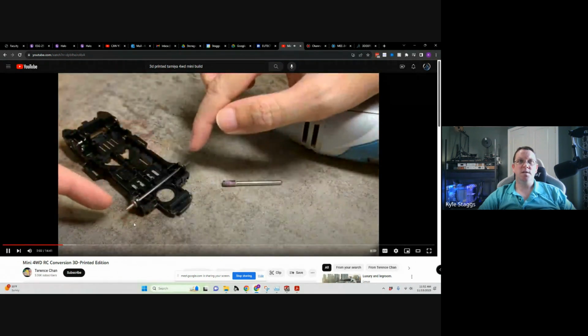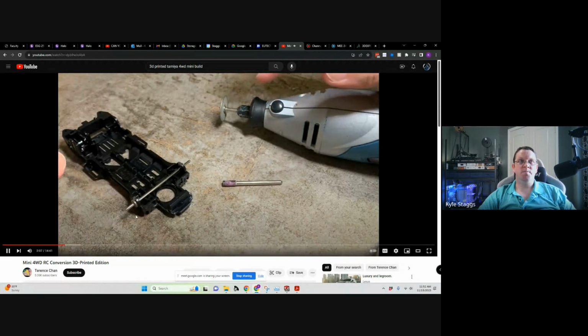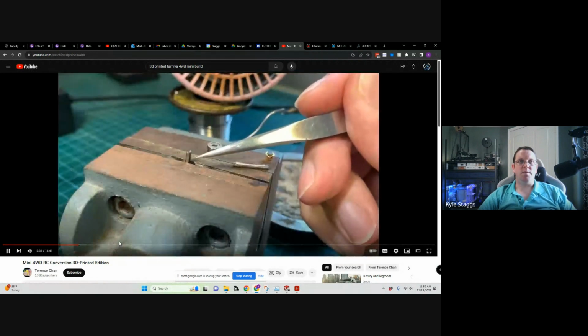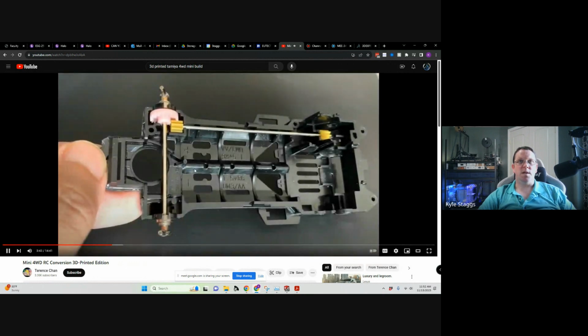Interesting. So they took some design principles and did some modifications. This is that drive shaft model idea that I was talking about, where you put a dual drive motor at the front or the back, put the batteries somewhere in the center, then have a drive shaft running up one side or the other. So definitely a thing that you can do.